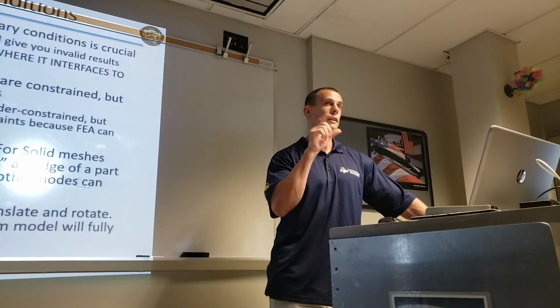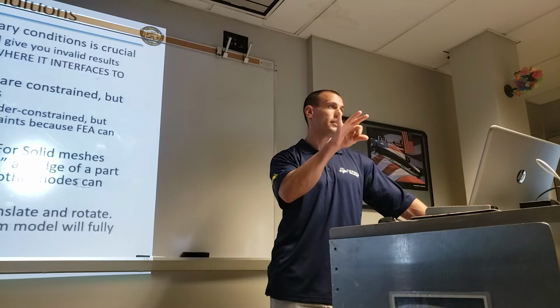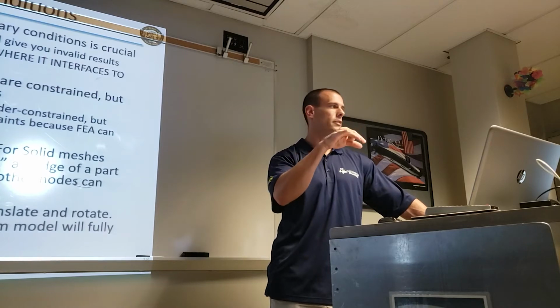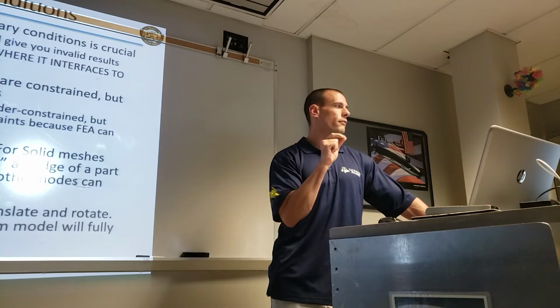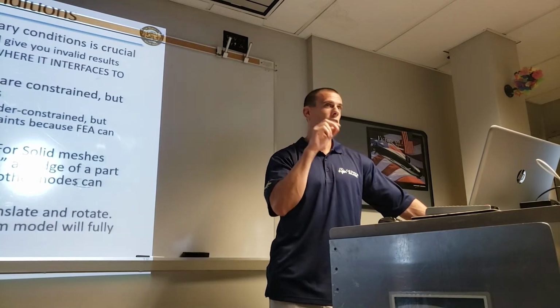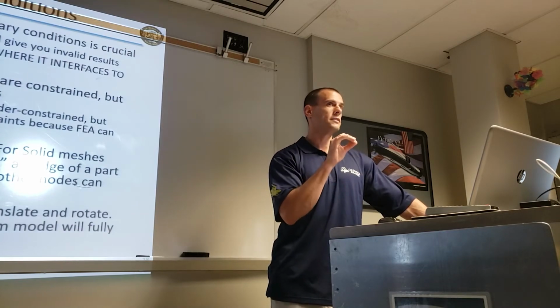When you do beam elements, it has 6 degrees of freedom at the node. So you can constrain 6 degrees of freedom. But for a solid mesh, it just has 3 degrees of freedom. So if you do fix, you're fixing all just translations of nodes.